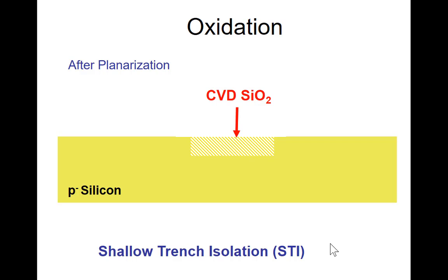On the previous page you were given the heights of some different materials, and then you do the CMP. It non-selectively takes away the top part of the whole wafer until it reaches that dashed line level. It's non-selective, it just scrubs away.